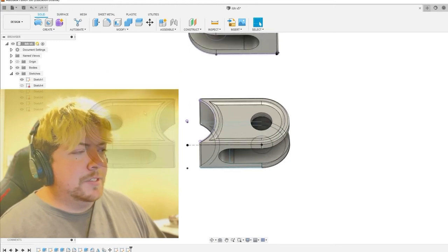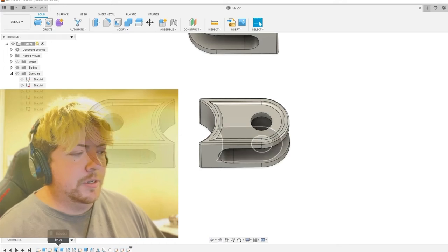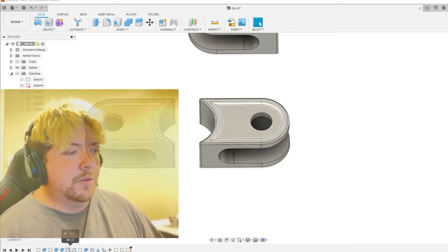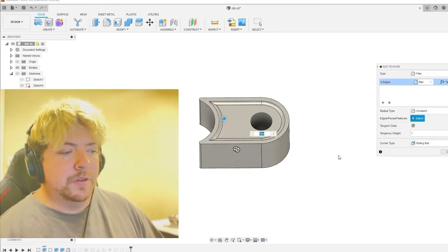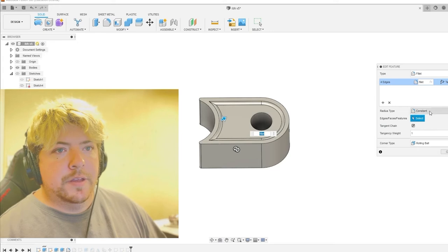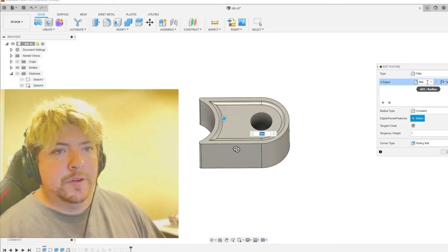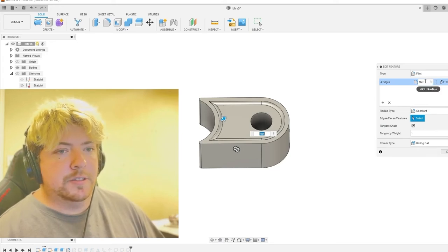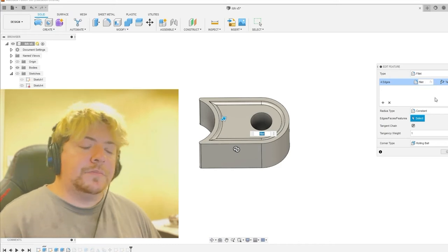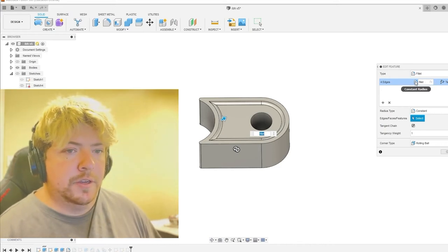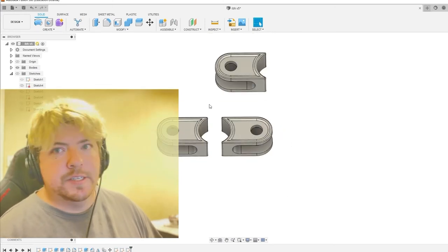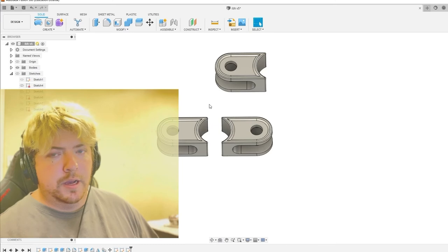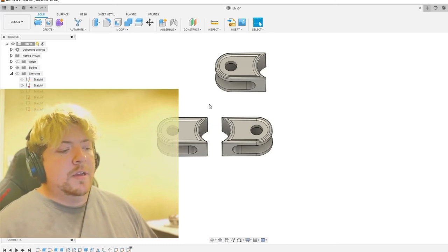Unlike 3D stuff that isn't necessarily seen in a 2D sketch, you can change and add as a parameter here. So like this fillet right here, I can go to edit feature on the history, and then I have the fillet function in there, so that's in my parameters as the value for the fillet. So I just leave that. But anyways, this makes design and making changes a lot easier after the fact.